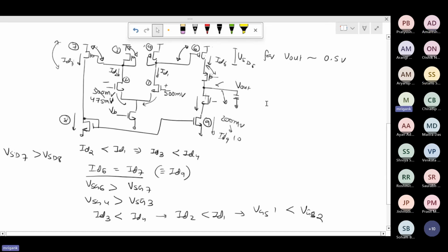So this is the reason, because the value of lambda is affecting the circuit, but I don't remember any such scenario in the advanced technology nodes that we have used in Cadence, because the TSMC model that we are using probably doesn't have that kind of a larger lambda. In this model, whatever lambda we get, we have to simulate accordingly. So assume you have a bad technology with a large lambda value, because of which channel modulation is significant, and then you have this kind of difference in the DC. But generally, I have not seen this kind of big difference in TSMC models.